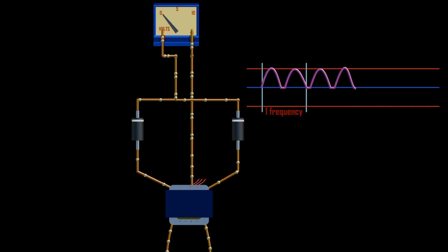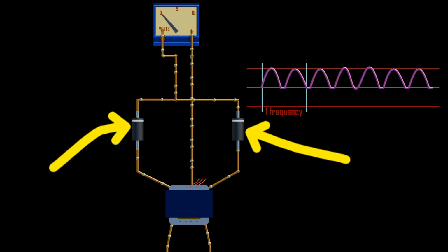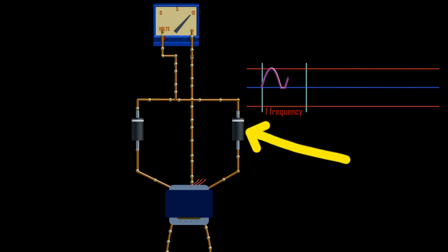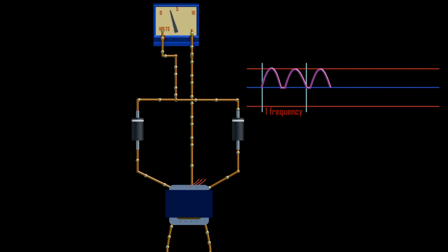This is how two power diodes can be connected together to form a full-wave rectifier that converts AC voltage to pulsating DC. With the help of a center tap transformer, we can connect the diodes such that when one diode conducts current, the other one blocks the current. Similarly, when the other one allows current, the first diode blocks current. This type of rectifier circuit is called a biphase rectifier circuit. We will receive pulsating DC with positive half cycles alone.